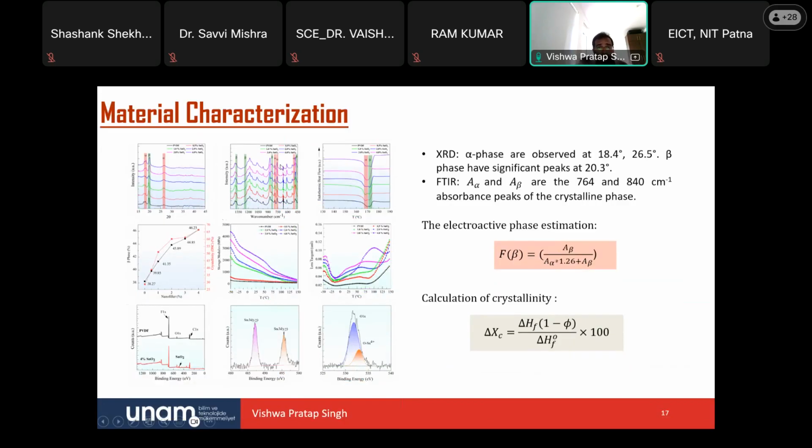And again, we have also done the FTIR. Here, the case is very clear. I think it would be better if I could zoom it, but that's okay. So you can see here, this is the pure PVDF that has been developed with the solution cast process, or after the thermal drawing. When there is no reinforcement, you have no pure beta phase peak.